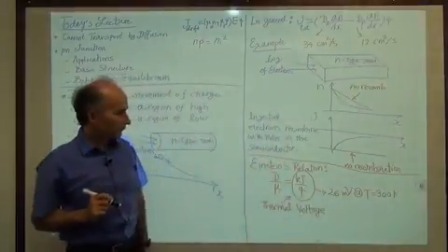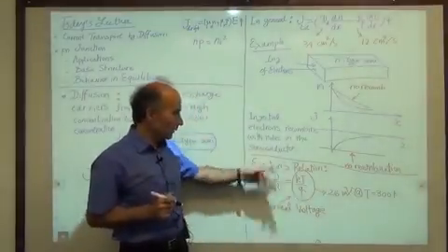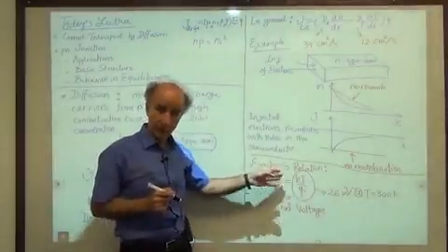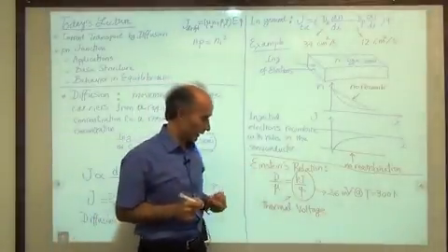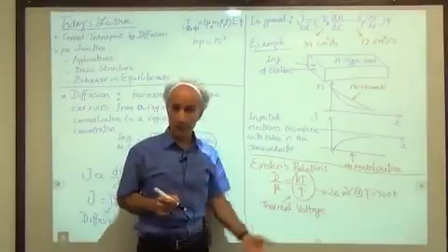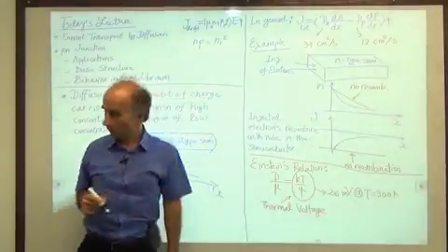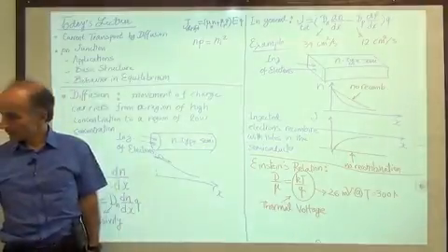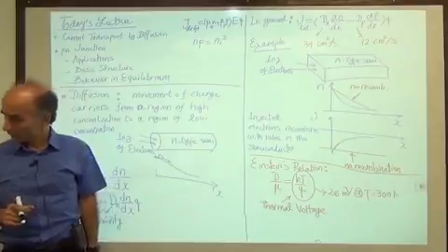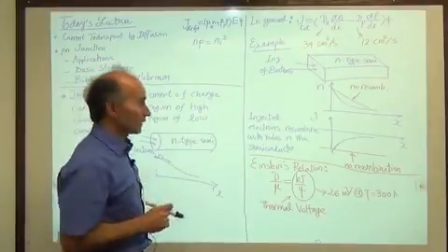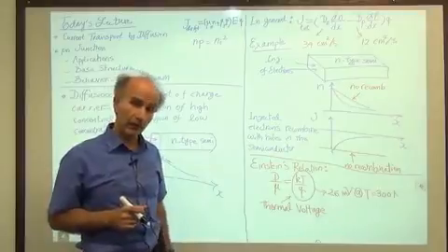Okay, so Einstein's relation allows us to simplify things. In case we end up with a ratio of diffusivity and mobility, we replace it with kT over q, and we carry this on. As you will see shortly, this appears in some of our equations even today. Very well. Let's see where we are. This concludes our study of charge transport or current transport in semiconductors.